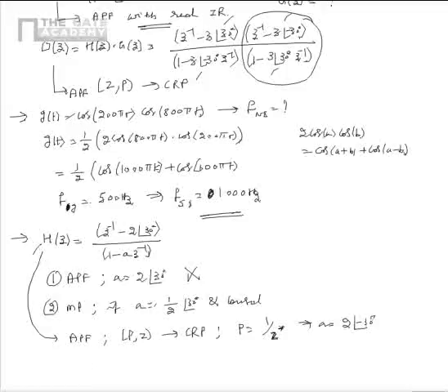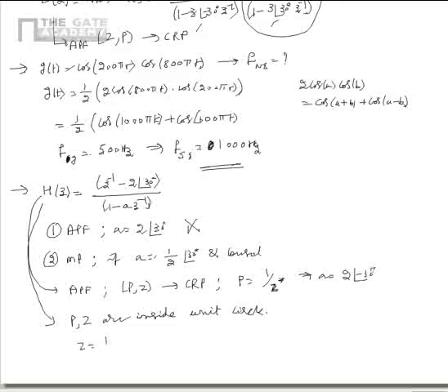Also, we can say that for the given system function H(z), if it is causal, it would be minimum phase if poles and zeros are inside the unit circle. From the given data, we see that the zero is at 1/2 at a phase of minus 30 degrees, which is inside the unit circle, and the pole P is equal to a, which is half phase 30 degrees, which is also inside the unit circle.